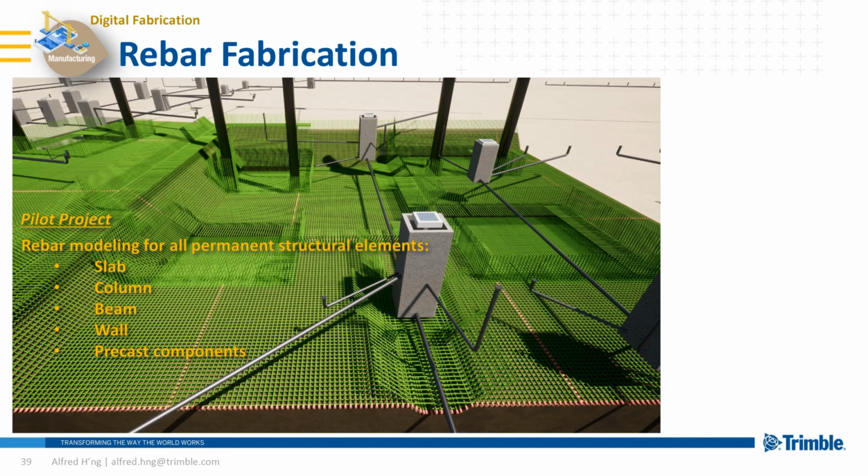So it's still a manual check and a manual BBS, but they get the information as a first cut to generate from. Okay, and now we are currently at the third step, where we think the rebar information is already accurate, trusted and checked. So we have more confidence and we think we're mature enough to directly generate the BBS from the model. So this is where we are now.